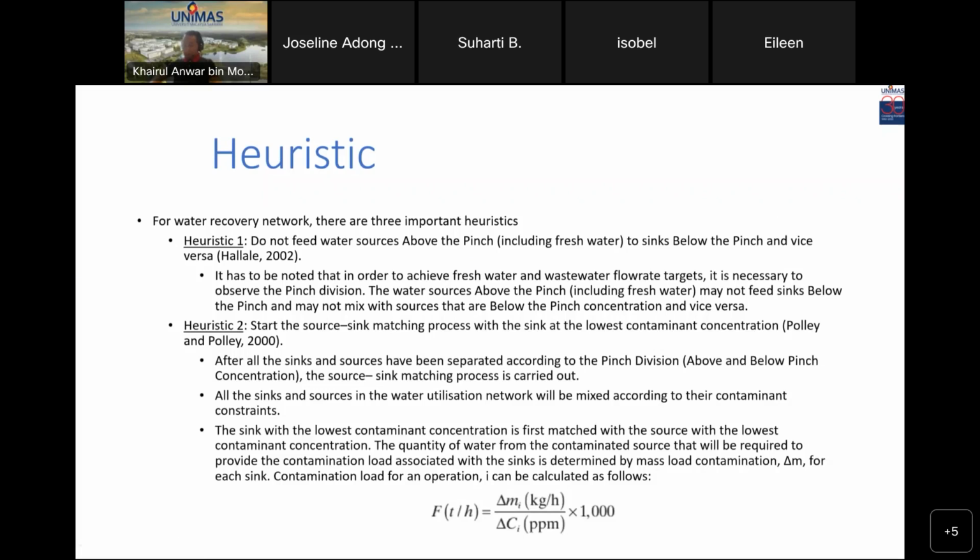First, do not feed water source above the pinch, including fresh water, to sink below the pinch and vice versa. This is just a rule of thumb to follow.